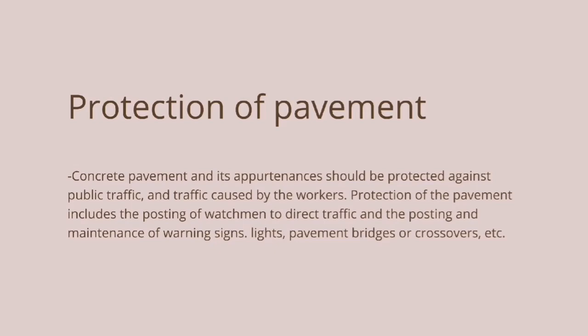Protection of pavement. Concrete pavement and its importance should be protected against public traffic and traffic caused by the workers. Protection of the pavement includes the posting of watchmen to direct traffic and posting and maintaining of warning signs, lights, pavement bridges or crossover, etc.